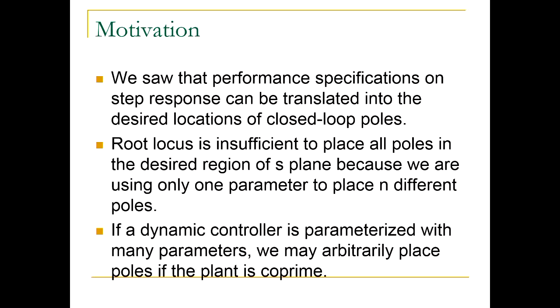So in today's lecture, we want to place poles anywhere in the complex plane, right? Where obviously, whenever we have complex poles, we will insist that we also have the complex conjugate, because in the end, the plants that we will be dealing with will lead to transfer functions that are rational with real coefficients. And in that case, poles would always appear in complex conjugate pairs.